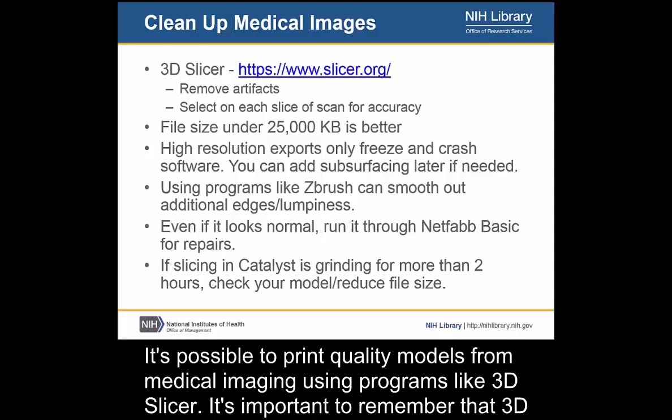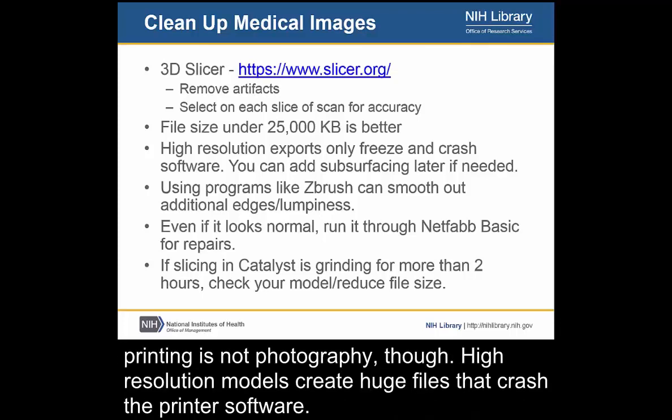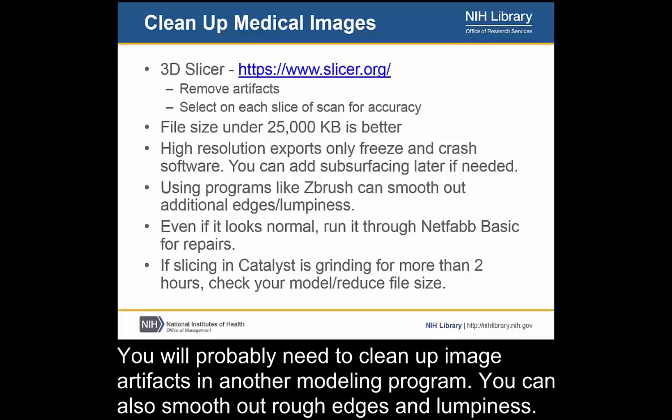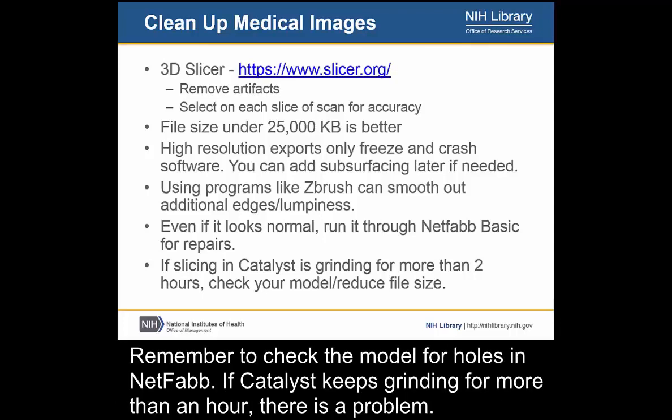It's possible to print quality models from medical imaging using programs like 3D Slicer. It's important to remember that 3D printing is not photography though. High-resolution models create huge files that crash the printer's software. You will probably need to clean up your image artifacts in another modeling program. You can also smooth out rough edges and lumpiness. Remember to check the model for holes in Netfabb.